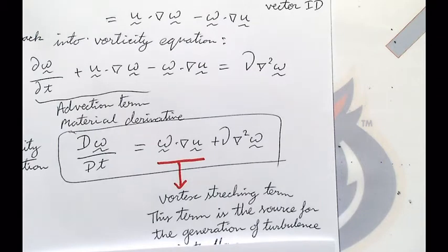That's fine. So when you talk about turbulence, at low Reynolds numbers there is no turbulence. Things are laminar, they are very clean. You talk about flow over a cylinder. It's very laminar flow until you hit, let's say, Reynolds number 6,000, 7,000. It's unsteady, it's shedding, but it's laminar. Turbulent is after 200. No. Turbulent wake. The wake is unsteady after 200. After 40, just 40. After 40 it is unsteady.